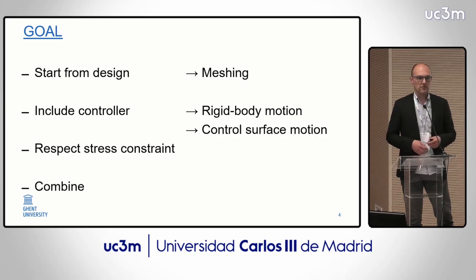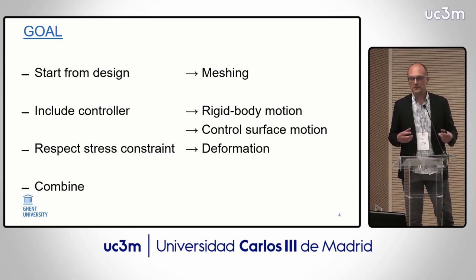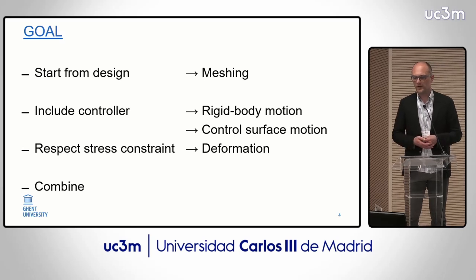We need to handle the rigid body motion to follow the trajectory prescribed by the controller. And we also need to take into account the motion of the control surfaces affecting the aerodynamic forces. When you want to respect the stress constraint, you need to be able to calculate the deformation and the effect of that deformation on the aerodynamic forces. And to combine multiple devices together, you need modularity. So those are a lot of requirements for the aerodynamic force evaluator.